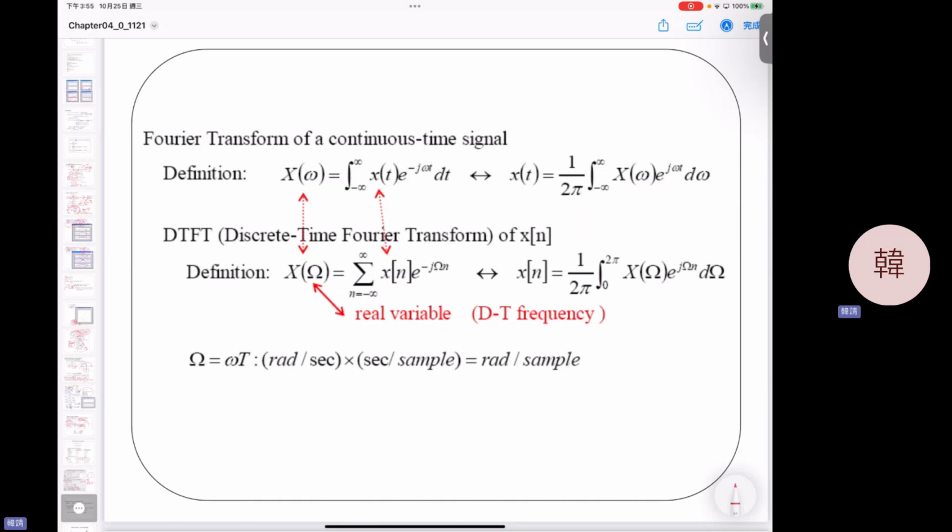We mentioned we went from Fourier series to Fourier transform, and then we are going to sample our signal into a digital signal with a comb function, and it becomes digital. So actually this one can be changed to this one. We call it the discrete time Fourier transform, DTFT. Why discrete time? Because you sample.